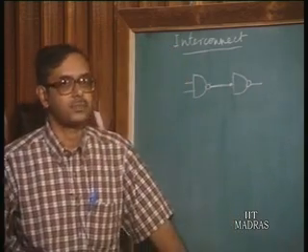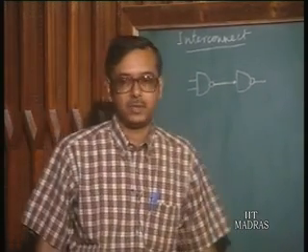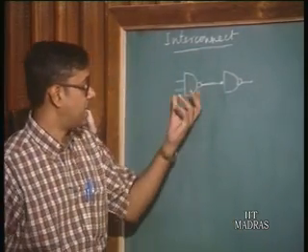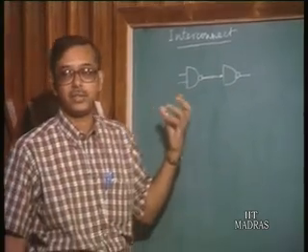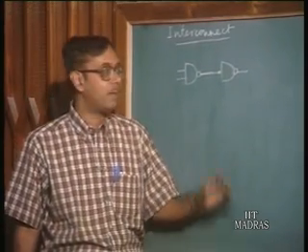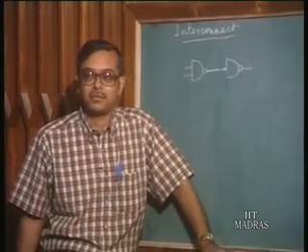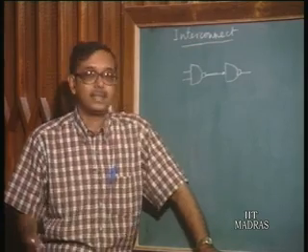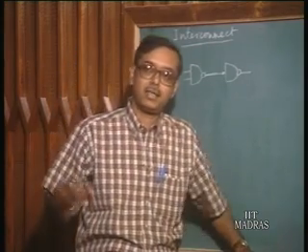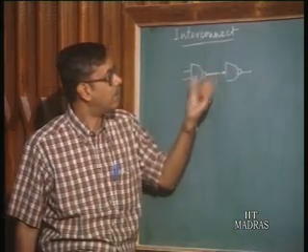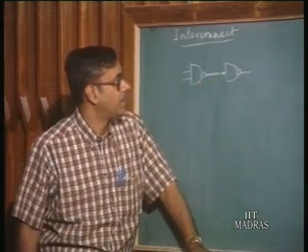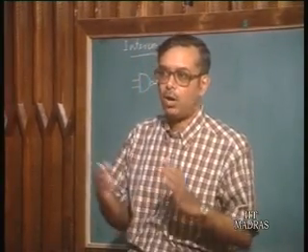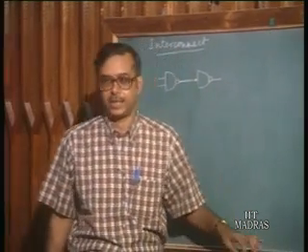The interconnects have a lot of effect on the performance of digital circuits, especially in today's world, where with the shrinking of device dimensions, the gate delays have reduced tremendously, while the effects of the interconnects have remained as before. In fact, the delays of modern day integrated circuits are controlled to a large extent by the effect of these interconnects. So in today's class, we shall take up the effect of the interconnects on the performance of digital integrated circuits.